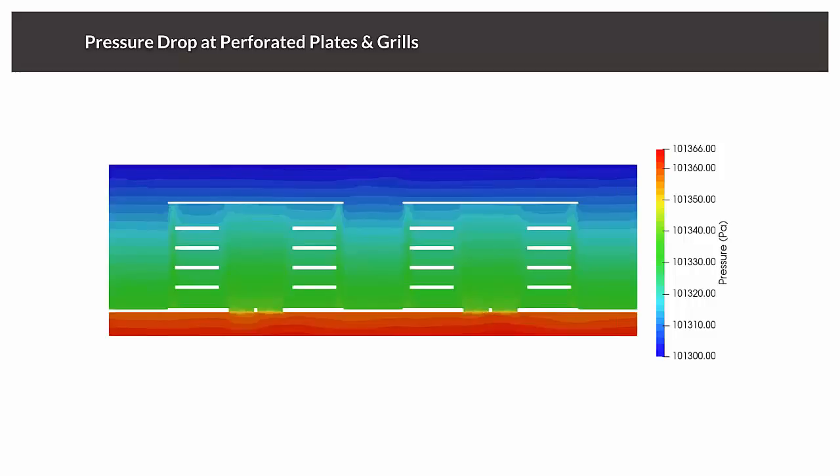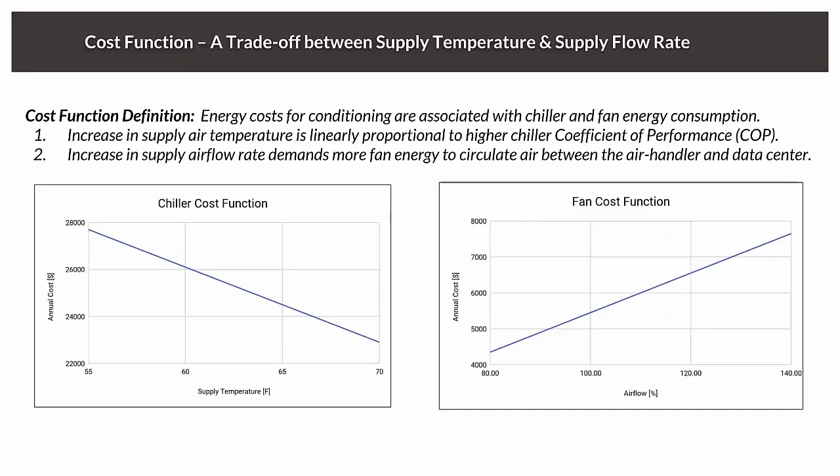So we are modeling, in this case, steady state simulations that we provided here. Of course, you can run also transient analysis on SimScale, but most importantly, this is actually the physical time that we as users had to wait while the computers were grinding a lot of what we call core hours, which was 96 times 3 times 16, since we had 16 cases.